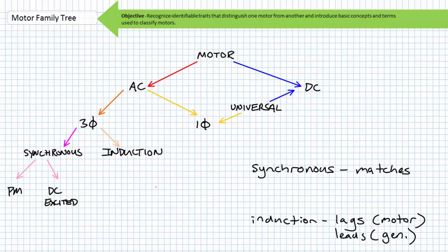Inside its operational range, a synchronous motor can be expected to match synchronous speed of the rotating magnetic field regardless of the applied load. Obviously, the electrical input requirements will change because increased power output requires additional input from somewhere. These devices are not magic though, and have practical limits under which they can perform as advertised.